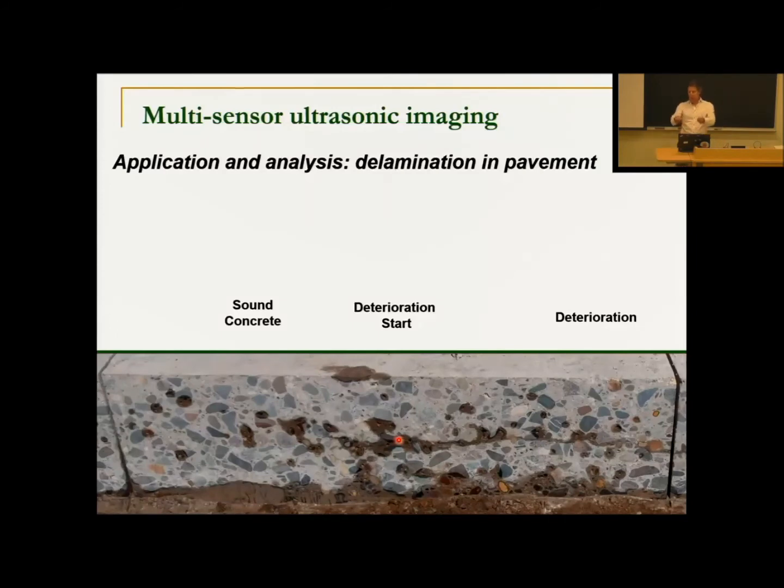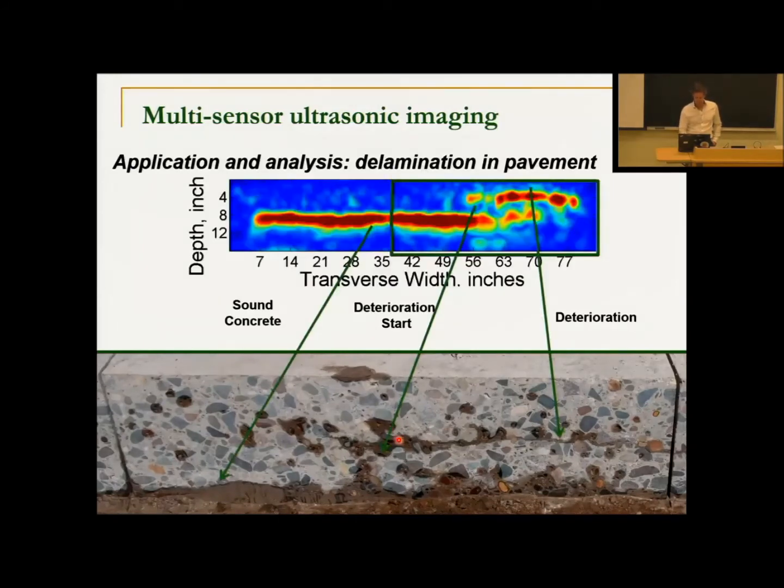So if we did a series of those ultrasonic data collections with reflected shear waves and the other waves, and we use an algorithm, SAFT for example, to reconstruct what that could look like, we get something like this. This is the reconstruction of that cross-section, which could give rise to something like that.